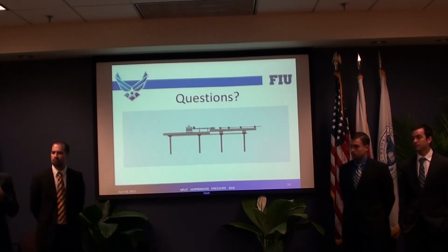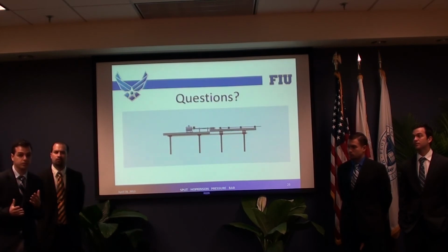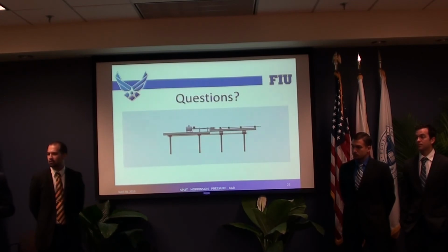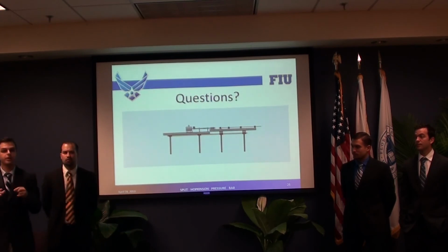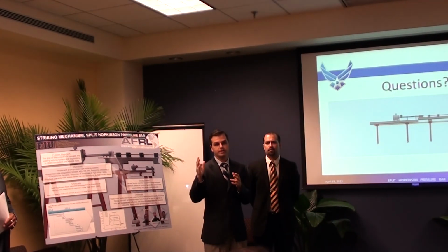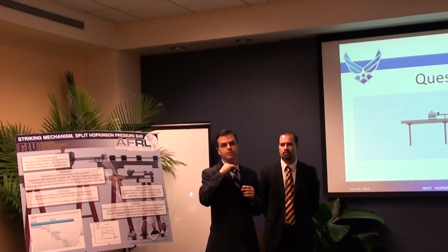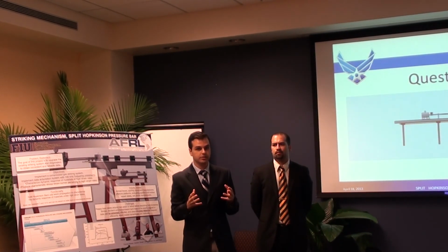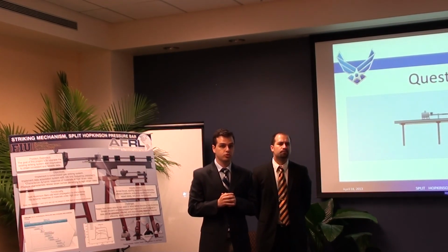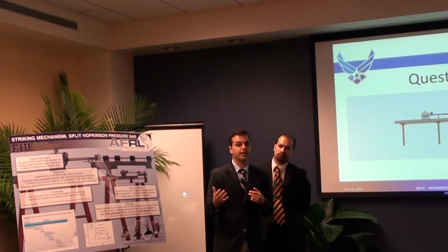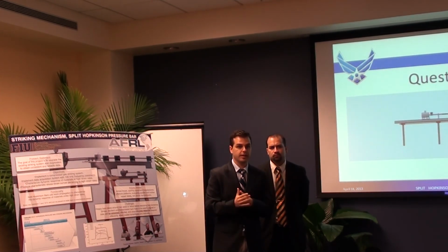Now, last year's team used a 4 kilohertz oscilloscope. That would come into play down here, where you can't really see it too much, but you don't get more points. You get approximately 1 point every time the stress wave has transmitted and reflected back 3 or 4 times. So you don't get enough data to analyze the system. You have to have a minimum frequency in order to get as much data and analyze the stress strain curves.